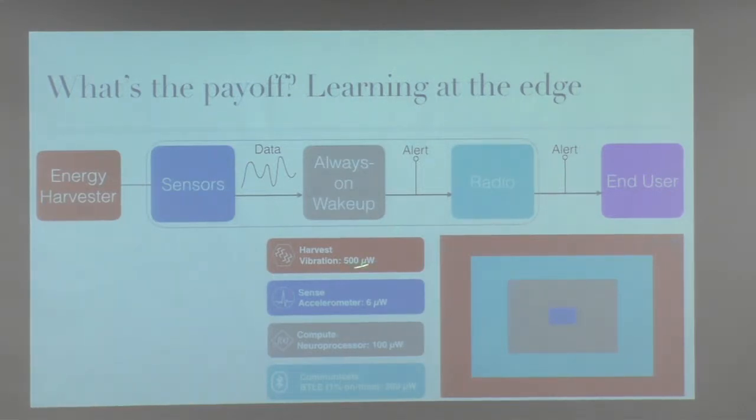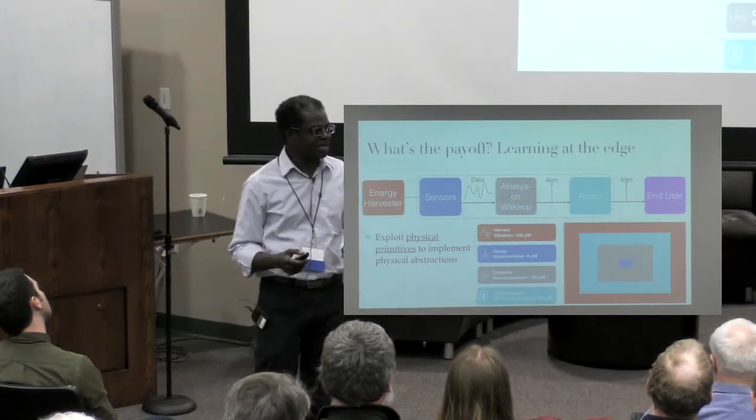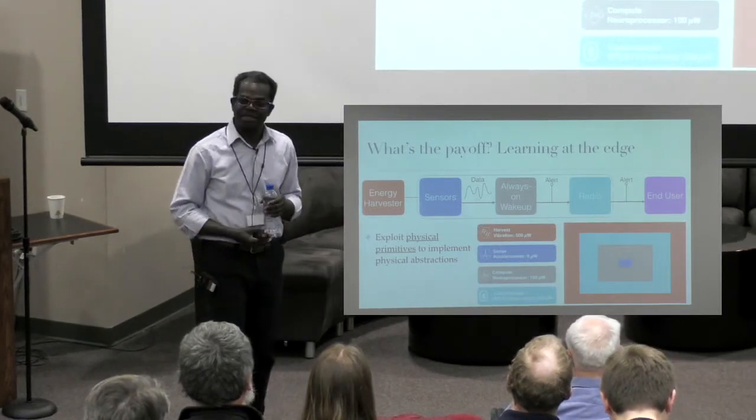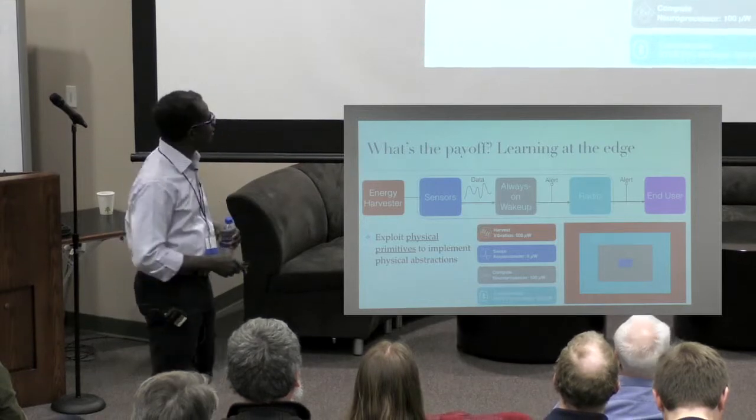And the key part of making this happen is these kinds of smarts that can basically predict what's happening in the environment with these naturally occurring signals. And the idea is that the most efficient way to do this, right now people are saying they can do this for milliwatts, but digitally, but you want to get down to microwatts or even fractions of a microwatt, basically the kind of energy that a pacemaker uses inside the heart, so that you only have to do surgery every 10 years to replace the battery. OK, that is like 70 microwatts.